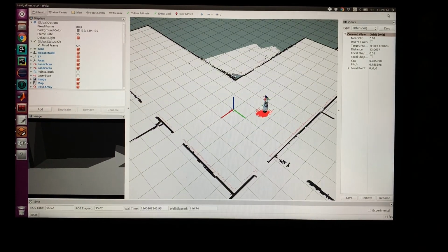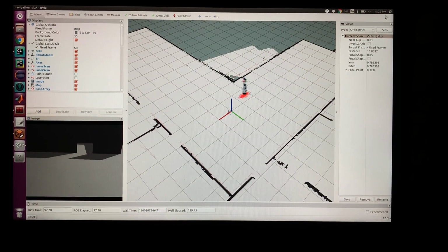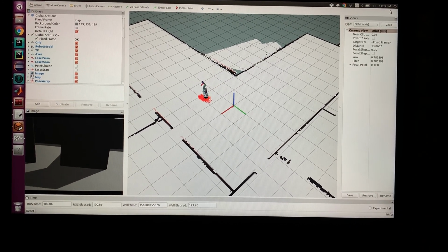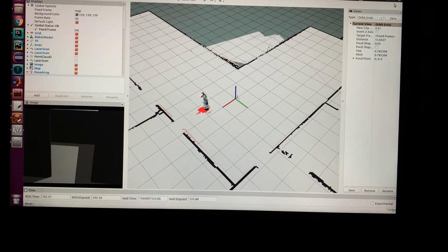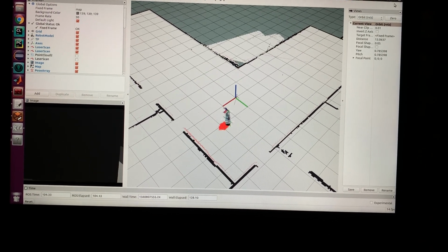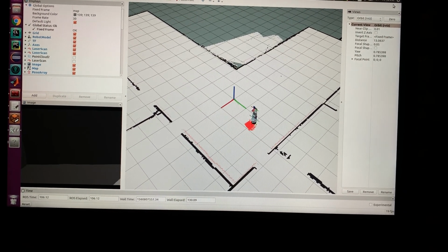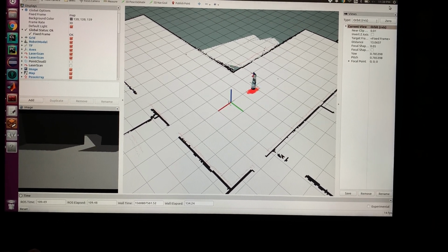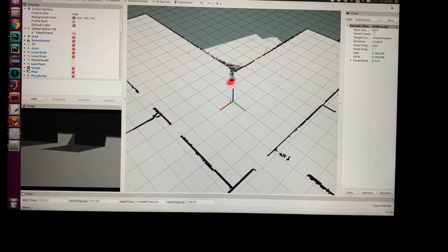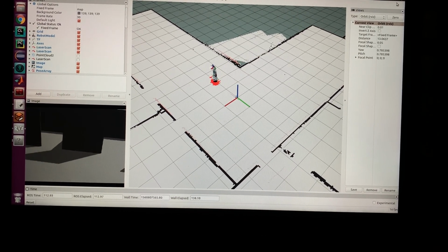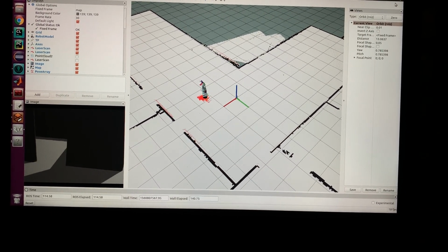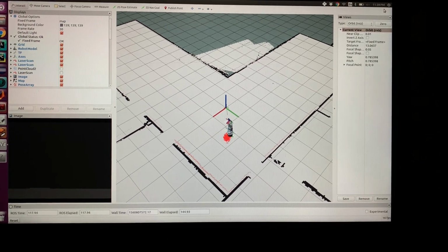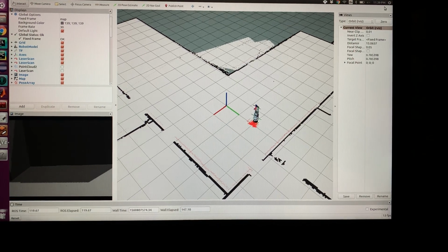And looking at the RViz, the reason for the small deviations from the path is mainly due to the localization, hence the state estimate, where we can see the arrows, which indicate all the particles from the particle filter, are scattered around the actual location, the state estimate itself. And this might explain some of the deviations that we see around the desired trajectory.